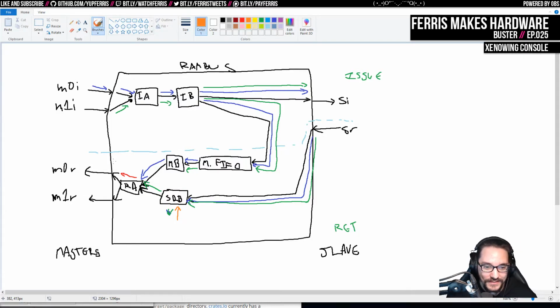One of the reasons why I wanted to tackle that at the FIFO level is because, first of all, then I don't have to add additional buffer stages. What I could do is make this a FIFO, and this return buffer could also be a FIFO, and then I could have another buffer there. So if I had a parallel FIFO here, then it would make sense. But I thought if I solve the write through problem on the FIFO, then not only do I get lower latency every time I use the FIFO, but I also don't need this secondary FIFO. So let's go back in time.